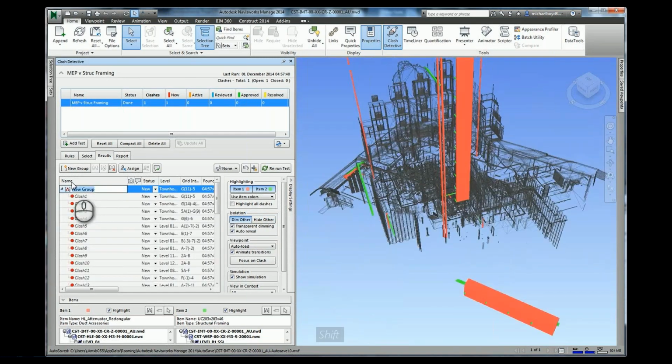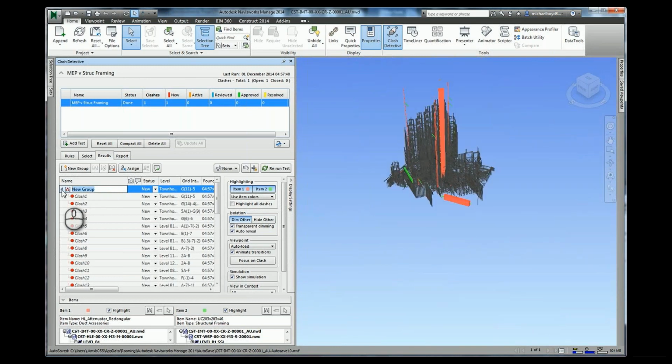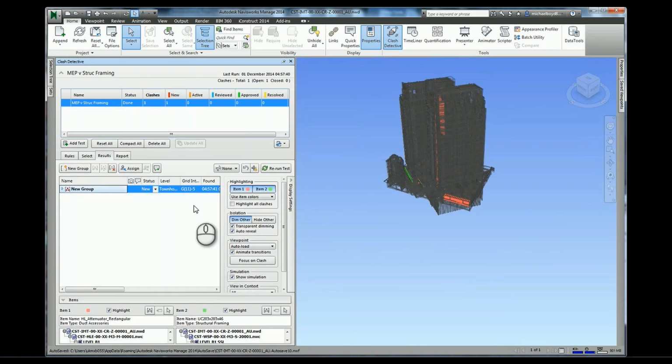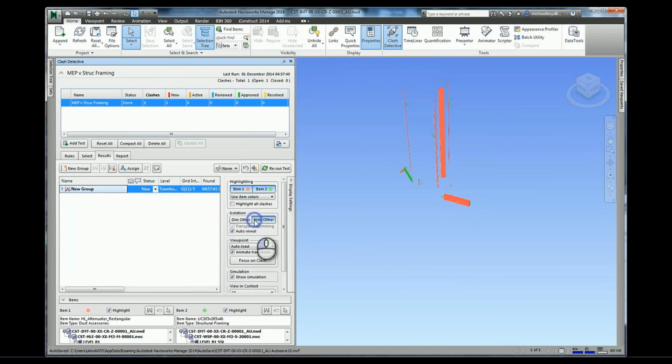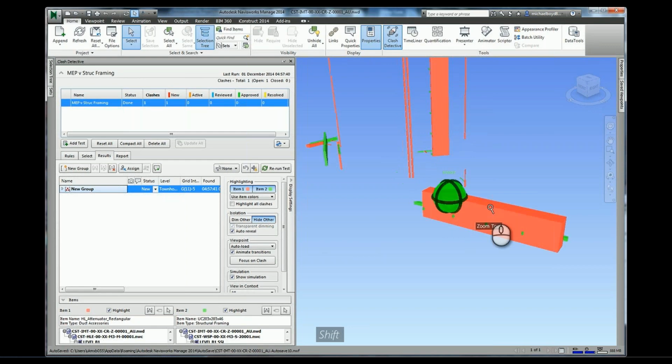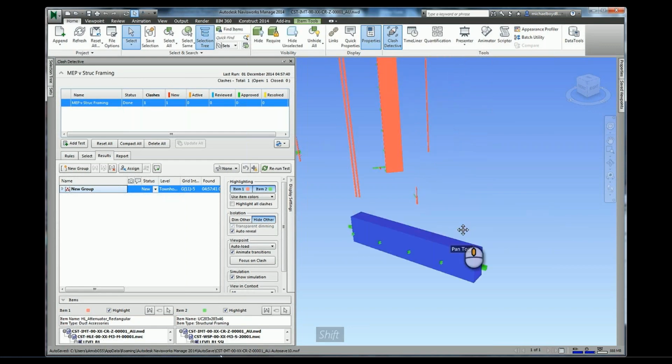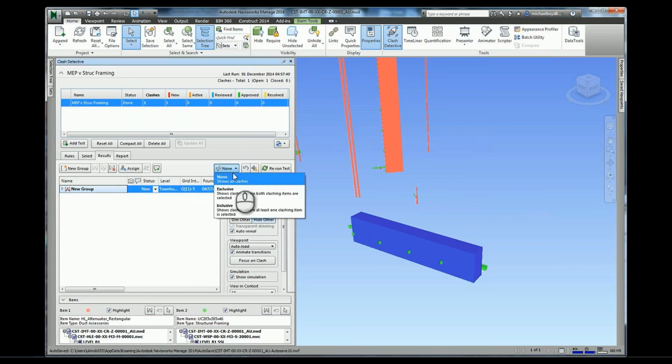Right, so we selected all those clashes in that clash report, right? Once that was saved as an overall group, we're able to go into the clashes, hide the rest of the model, and this is where I was showing you where we're talking about selecting an object and making sure it includes everything that it clashes with, right? So in this case here, I clicked on that object that has items that are clashing with it, right? In your dialog box, we went and set that to inclusive.